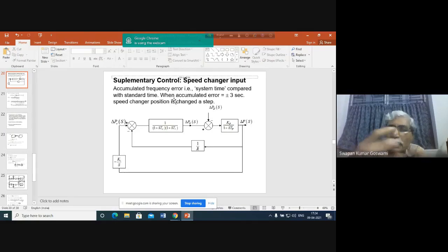If you draw extra power when the frequency is above normal frequency, then you will not be getting any price for that. How much you will be earning by delivering power will be reduced at higher frequency.